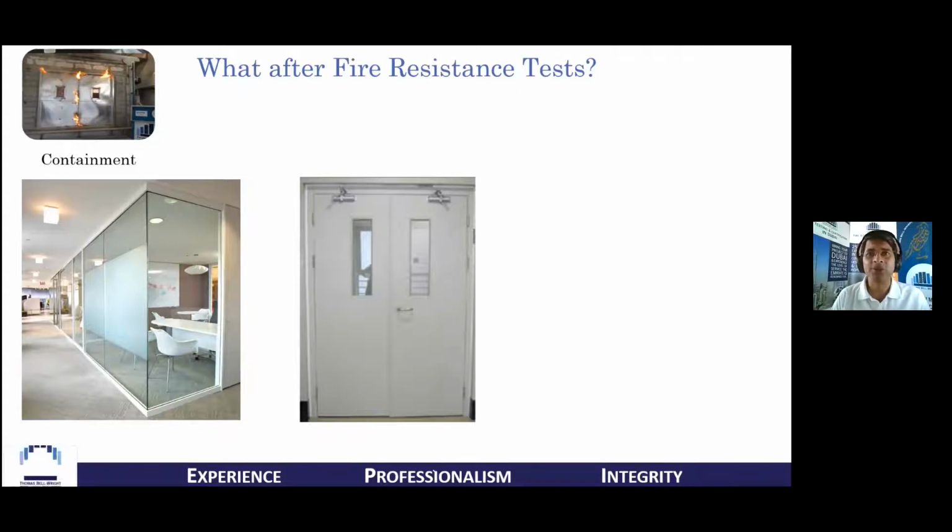And this is extremely critical because unlike measuring a commodity like maybe grains in a weighing scale or the flow rate through a pipe or even an electric cable, where what is being validated does not know it is being validated, versus when we are testing for fire resistance, the producer of the sample is aware that this sample is going to go to the lab and get tested. The installer of the product to be tested is aware that this system will face a fire resistance test. And this is a key difference which should be understood whenever we are seeing a fire resistance test report.